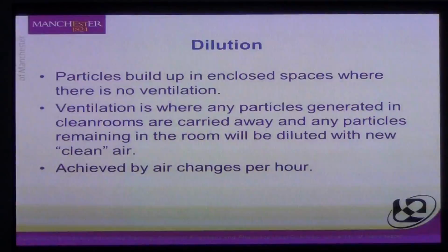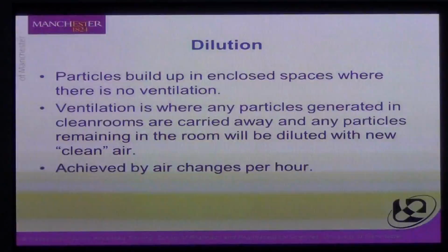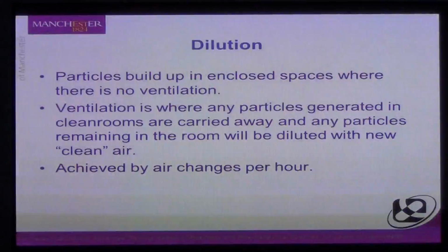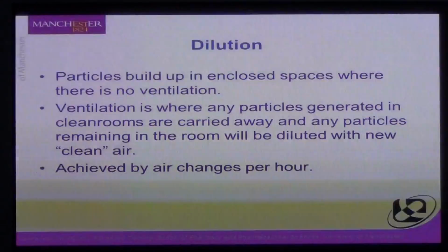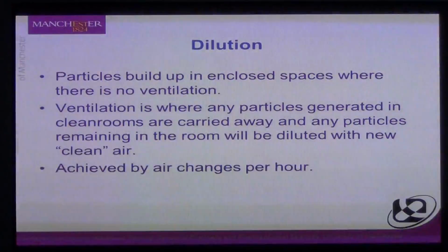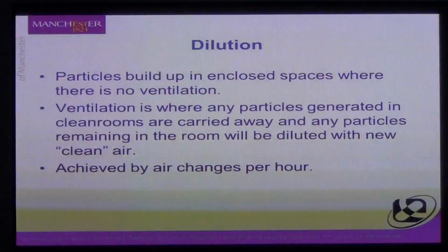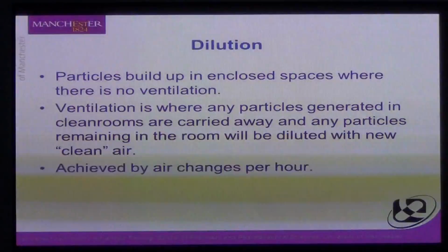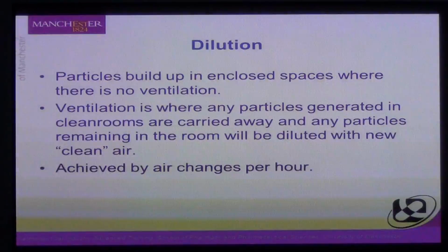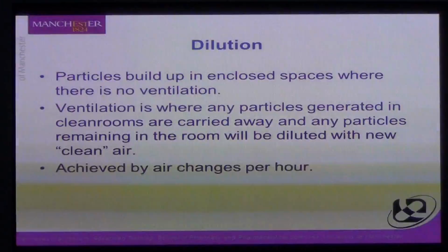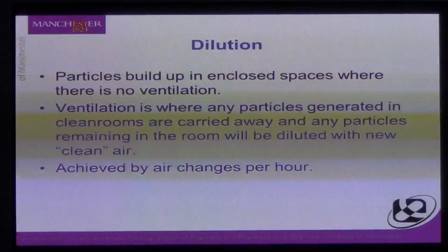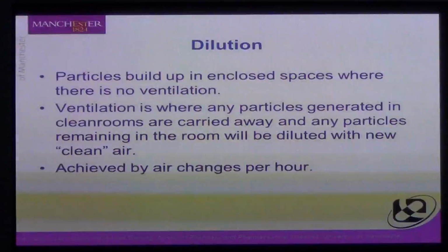Okay, our second key clean room concept is dilution. This is a natural thing: if we have a room without very much ventilation in it, particles are going to build up. So we need to create lots of ventilation in the clean room to ensure that particles generated in the clean room are carried away with clean air, and clean air keeps coming in, refreshing the clean room and helping dilute the particles out. This is achieved and measured by having a suitably high number of air changes per hour. A modern clean room would have at least 40 air changes per hour.